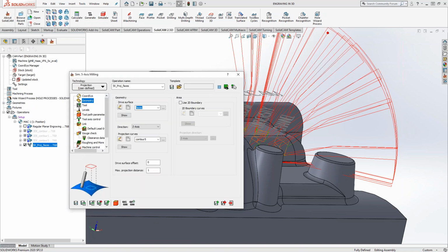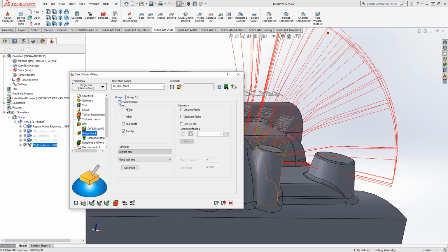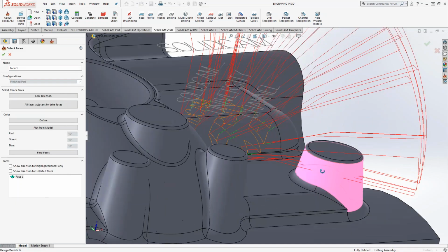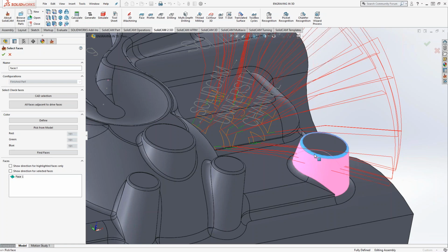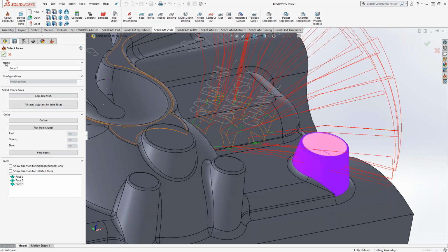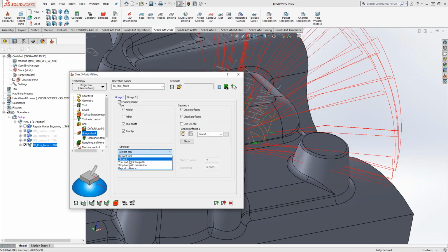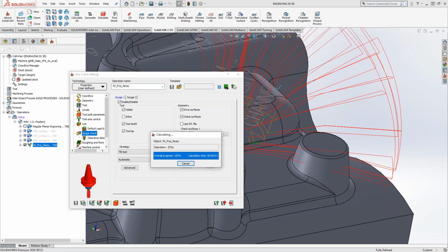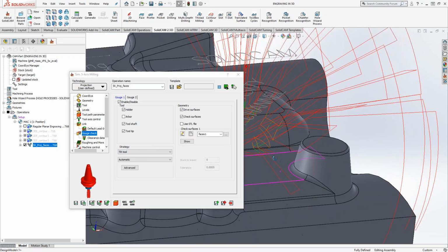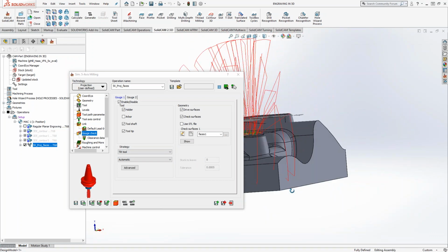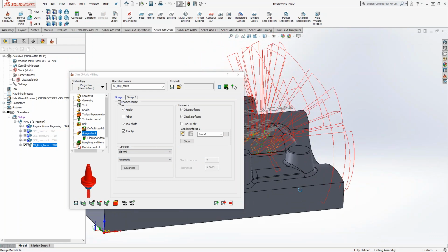Well, to follow with what Jake was asking about, we would use 5-axis because we want to make sure we don't crash into our part there. So in gouge check, I'm going to try and use the holder against some drive surfaces, which would probably be all these guys over here. And then we'll just tell it to tilt the tool in the case of a gouge. So you see there's some more tilting going on, some super massive tilting that's going to crash even more.